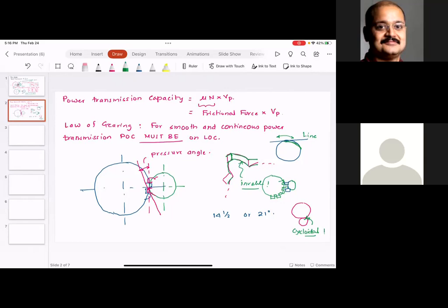Involute gears are commonly used for all applications like automotive and power transmission. Cycloidal gear trains are used in specialty applications, where you want less heat generated, very little noise, or where you have some critical measurement or specialty equipment with certain restrictions. So most commonly, involute profiles are used in gear cutting.